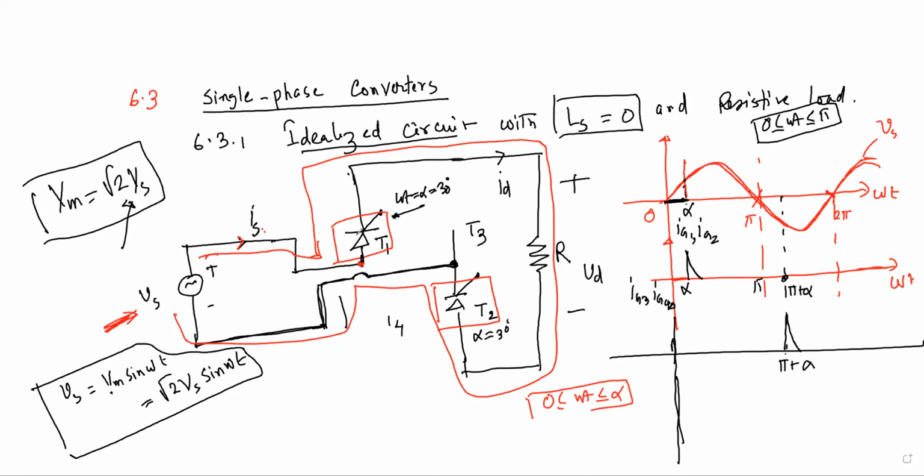So here, T1 and T2 will just work as a diode, right? We have given the video. Can you remember the video? We told that this is your anode, this is your cathode, your PNPN. Then when we have applied the gate pulse here, this P has become N, so it is like a PN diode. Right or wrong? Yes, sir.